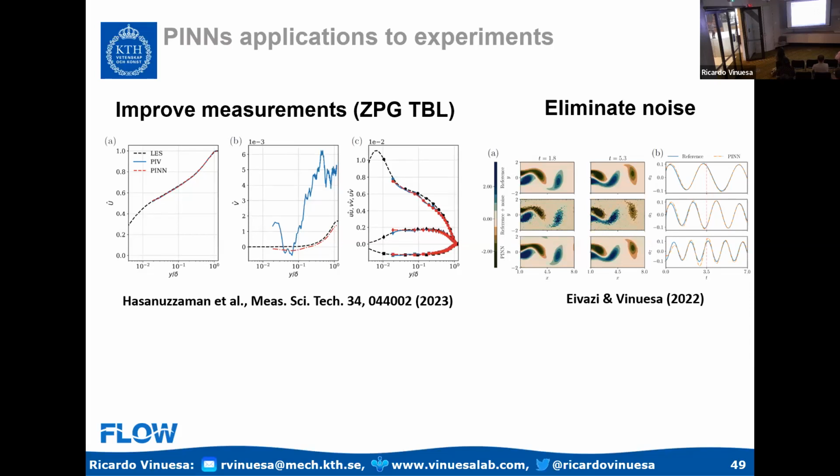Here, I'm showing you the temporal coefficient of several POD modes: the third, fifth, and seventh. This is for the case with PINNs. We can see that the third and fifth modes are in excellent agreement. We can really get rid of the noise and we get very good agreement. Even in the seventh mode, we agree pretty well. So we are able to do this quite effectively for this particular case, and this is of course a preliminary study. One can do something much more interesting with real data sets and with more challenging flow cases, but even in this simple wake of a 2D cylinder, we can remove some of the noise and get some robust results.